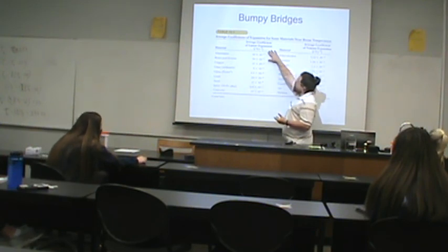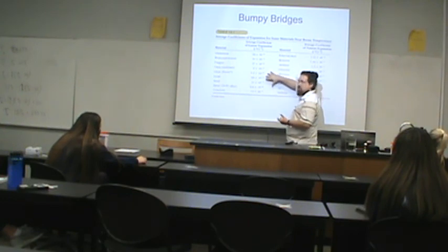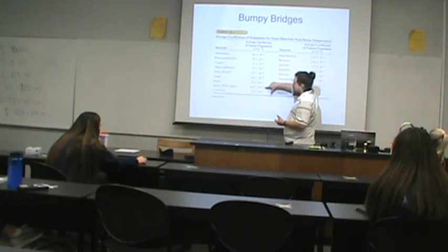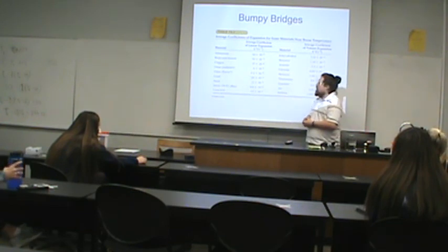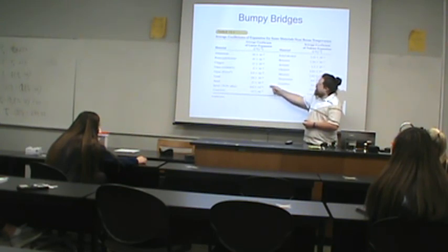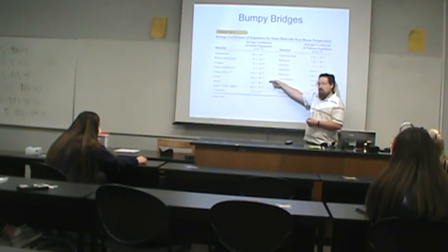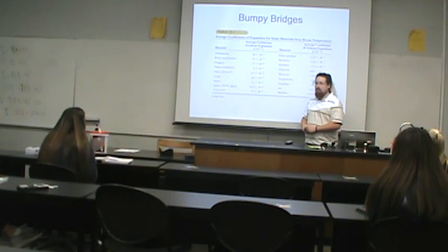So these are the linear expansion coefficients of 10 different solids. And among this list, the smallest number present is Invar, which is a nickel iron alloy. That does not come up much in one's existence, I feel. But Invar would expand at a rate about 30% slower than lead. So definitely don't make your structures out of lead. A, because expansion, B, because poison.